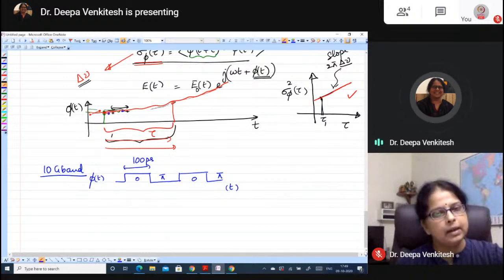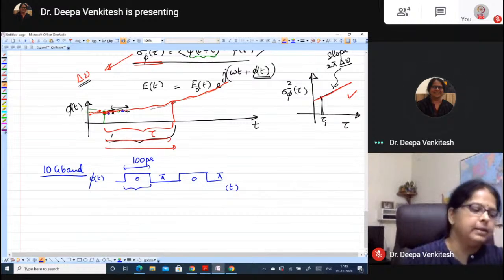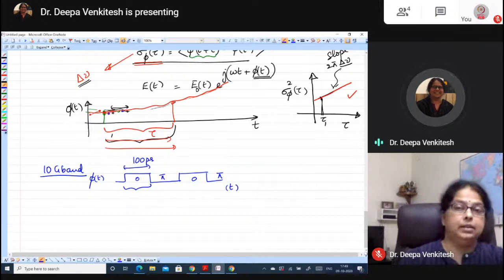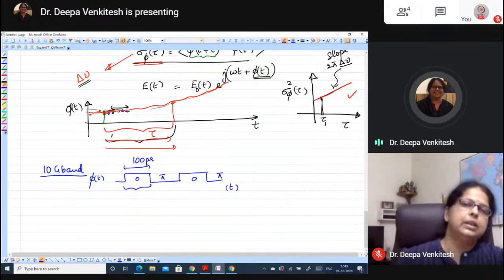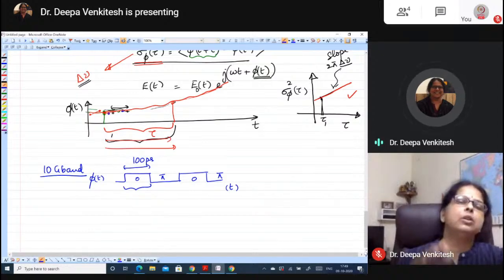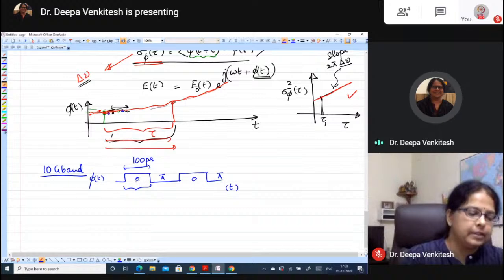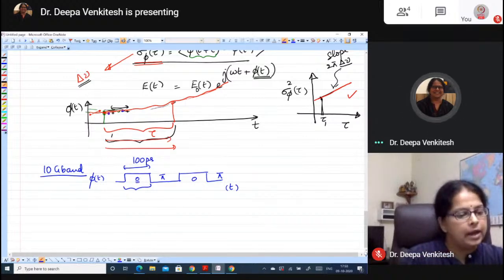What is my demand from a BPSK modulation? Within this bit slot, my phase should remain as 0, with respect to some reference phase. Of course, there's no definition for absolute phase. It's all with respect to something. So essentially, with respect to the reference, I call this 0, and I need this part of my time to maintain a phase shift of pi.